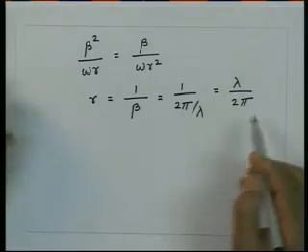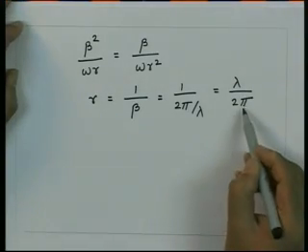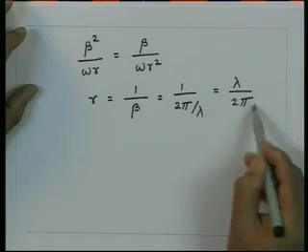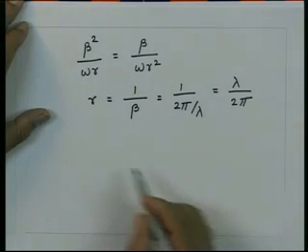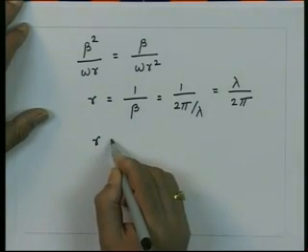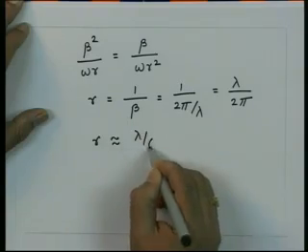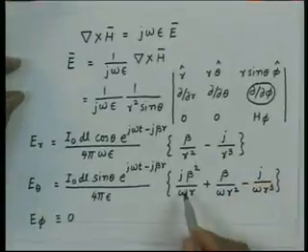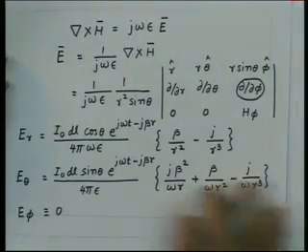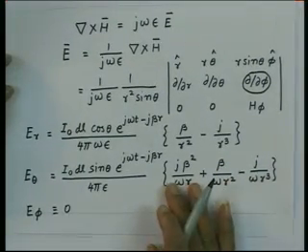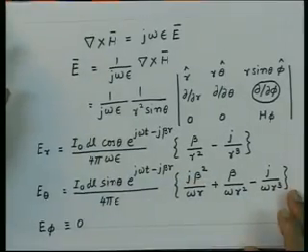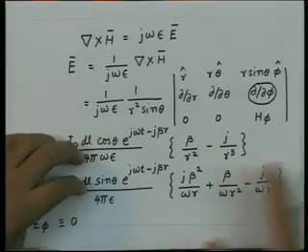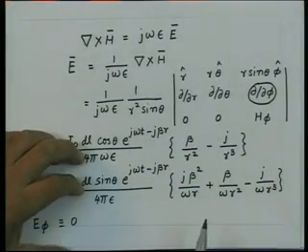Taking pi approximately 3.14, so taking this quantity approximately as 6, we say that approximately at r equal to lambda by 6, these three terms will become equal in magnitude. So, if I go from the Hertz dipole to a distance of approximately lambda by 6, then the radiation field, the induction field and the electrostatic field would be equal.